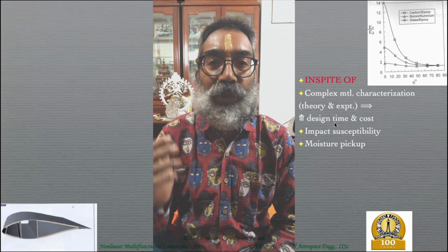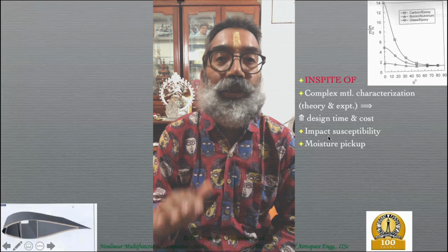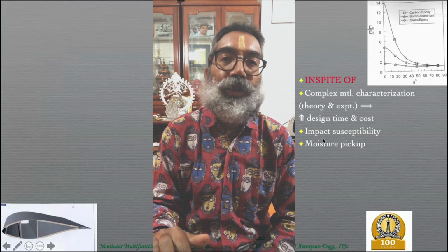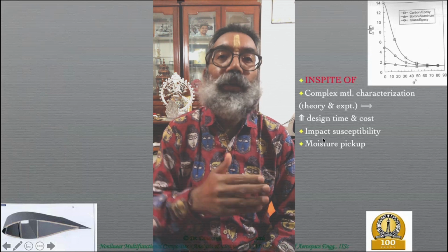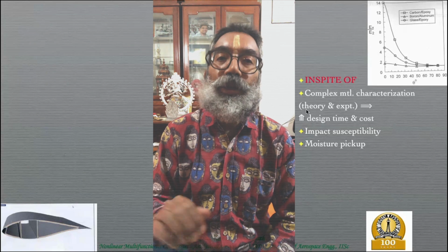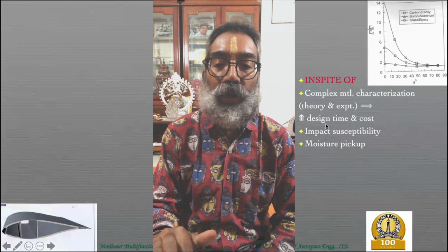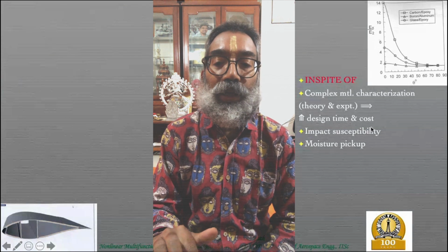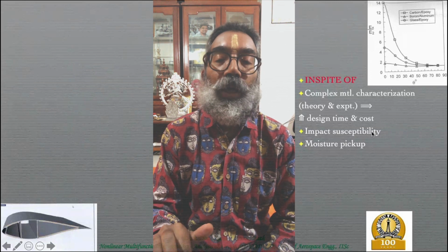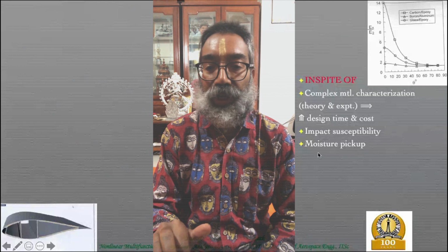But the reason I brought that out is that that has a much higher fracture toughness, energy absorption capability in impact, compared to other fibers like carbon fiber or glass fiber, etc. So you can use those to some extent in those regions where you know are much more highly susceptible to impact, rather than having a metal covering.